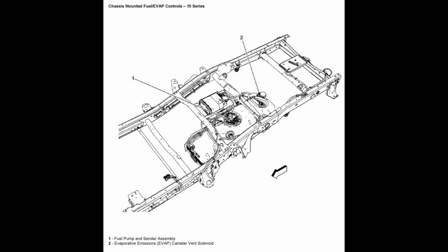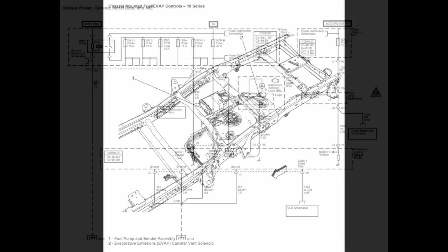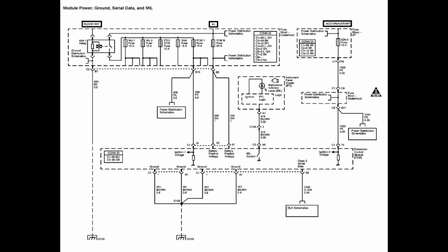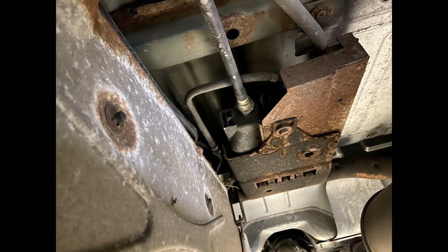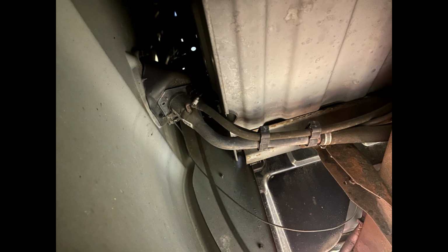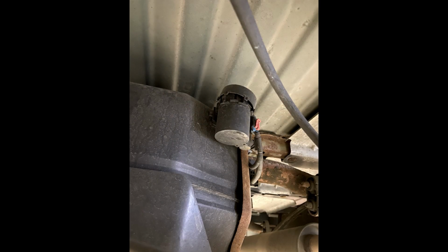The Silverado and the Equinox have very similar components for the EVAP system. Both vehicles have an EVAP canister, purge solenoid valve, vent solenoid valve, a fuel tank pressure sensor, and an EVAP service port. For the operation, they run the same tests: a large leak test, a small leak test, a canister vent restriction test, a purge solenoid valve leak test, and a check gas cap message that comes on your dash.